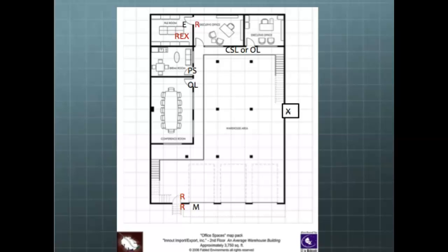I went with a reader. I just think it's easier. If you're going to put an access control system in, then you want to limit the number of cipher locks, quite frankly, because they're as expensive in the long run. An electronic one runs about $1,000. So does putting in a reader in many cases. And then you have to go to the site and program it. You can't go to the host and program it. You have to actually go to the lock itself to take people's codes out, those kinds of things. So I would stick with a reader there. That's the way I designed the building. Doesn't mean it's the way you design the building.